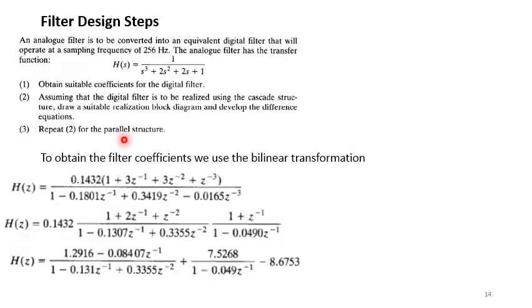So you understand that, based on the system function you have, you can express the system function as a rational system function, in which case you implement it in form 1 or form 2. Or you can express the system function in factored form.